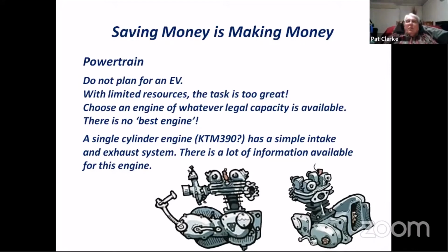Well, that means that when the throttle is opened about 30%, the area of throttle opening is equal to the area of the 20 mil restrictor, and so the restrictor is saturated. Any more throttle does not allow in any more air. However, it will allow more fuel, so the engine just drowns in fuel. The car is extremely difficult to drive. The throttle is like a light switch because you've got so little throttle movement for the car to operate in. The dead set giveaway of that is when the driver tells you, oh, when I lift off the throttle a little bit, the car seems to go better. Because as they lift off the throttle, they're leaning down the mixture and the car will go a little better.